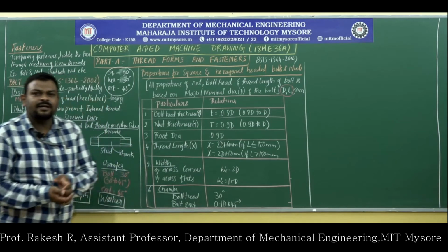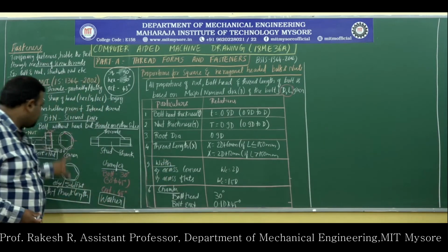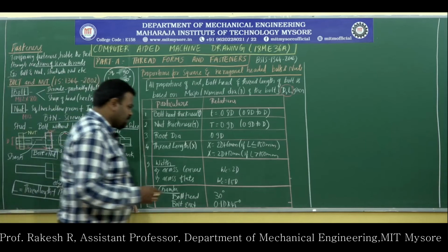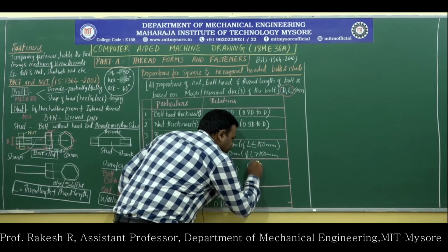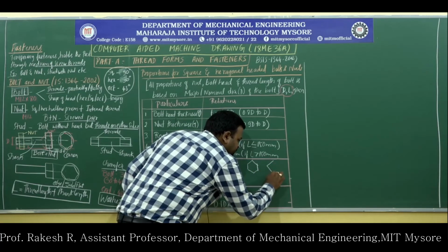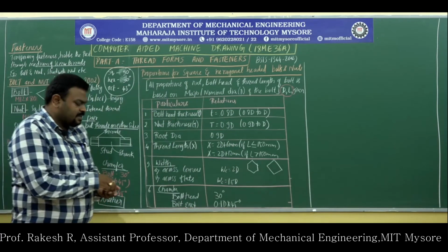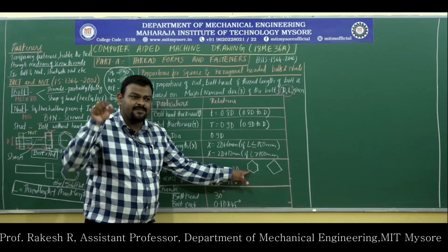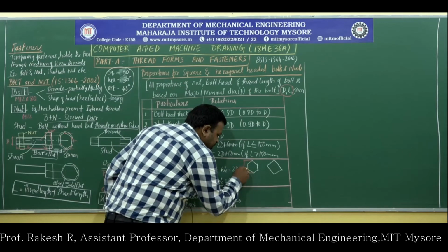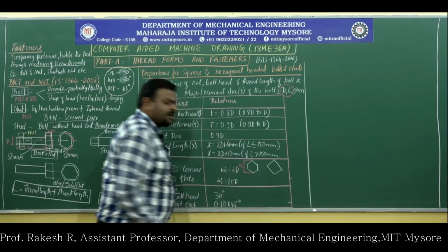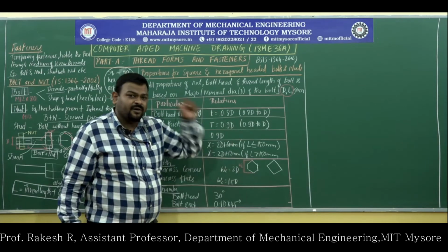And width. What is this width here? Here the width is the hexagonal width or square width. This is a hexagon and this is a square. Again, there are two things. When I place the hexagon like this, with a corner at the top, the width across the corner is 2D. I will mention that as width across corner, the corner to corner distance.